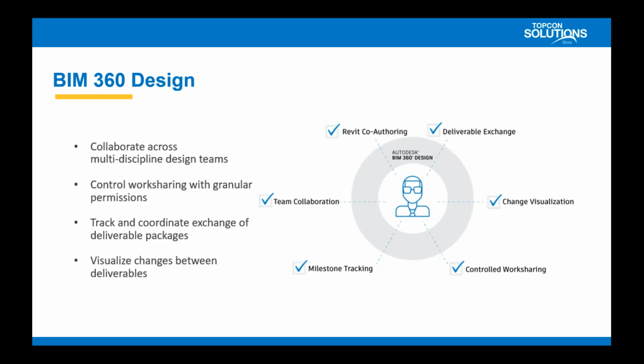So the interesting thing to think about here is that if you have an active model, like a central model or a Revit model you've been working on, and field teams need access to some of this model, they may not need access to the entire model, or even subcoordinators may need access to a portion of that model. This is where we can also use BIM 360 Design and that package creation engine in the design collaboration module to create those specified sheets and views, your publish settings essentially, inside of Revit. You're going to specify exactly what you're pushing up.